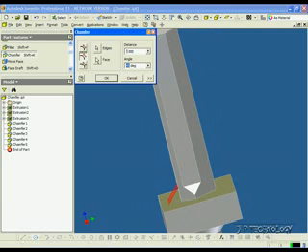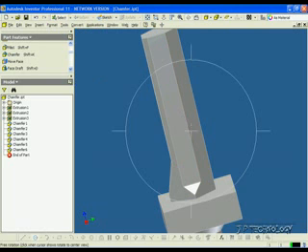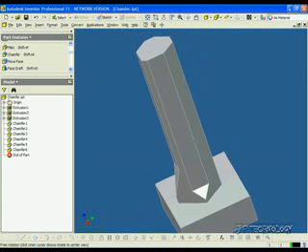Now the 45 is what we've been using already. Now we're able to change it. We can change it to 70, and it's a steeper one. And if we change it to 15, it's going to be a much shallower one. So let's change this to 70, click OK, and if we rotate it around, you can see that we chamfered it at 70 degrees.